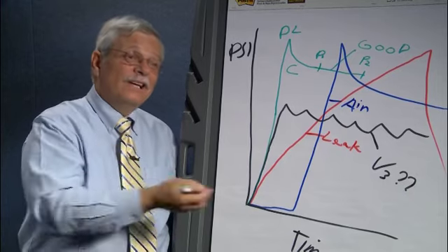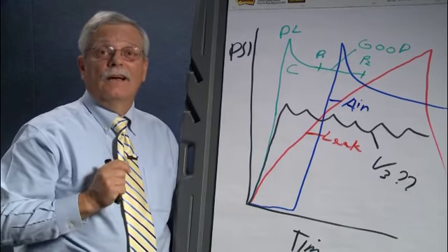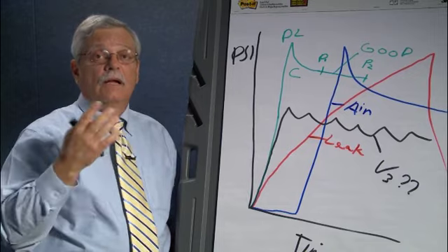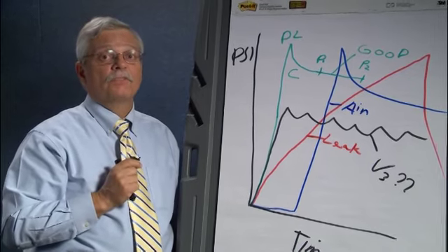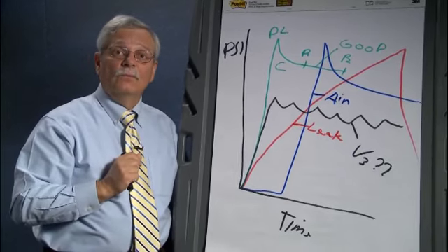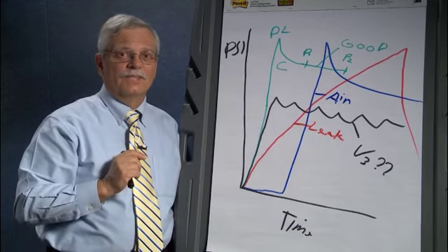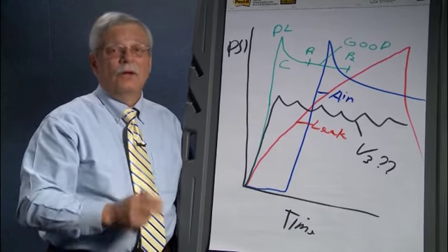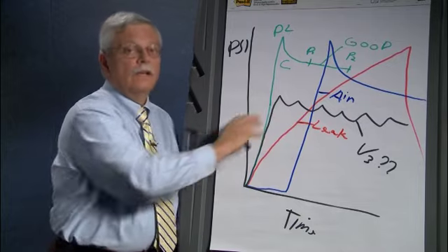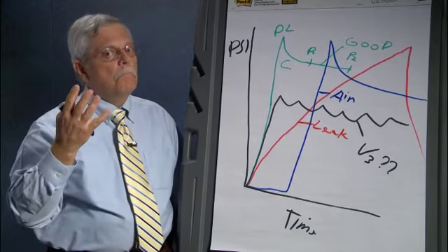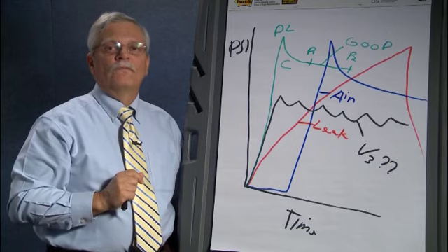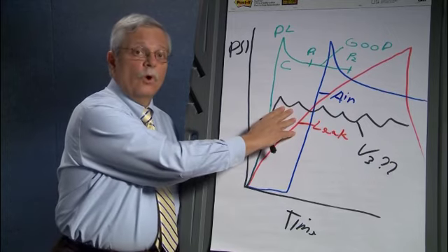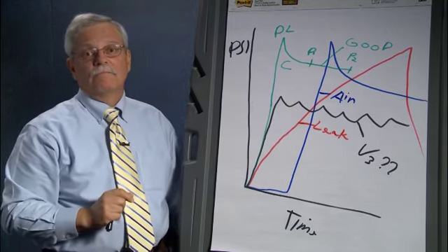And under pressure, we can't have a leak in one direction. We do that on a pump purposely. We put a device called a check valve in, which allows flow in one direction and not in the other. But effectively, flow is a leak. So this machine is still useful, but it might be on the way of failing. But you can still get good work out of a machine that's doing this.